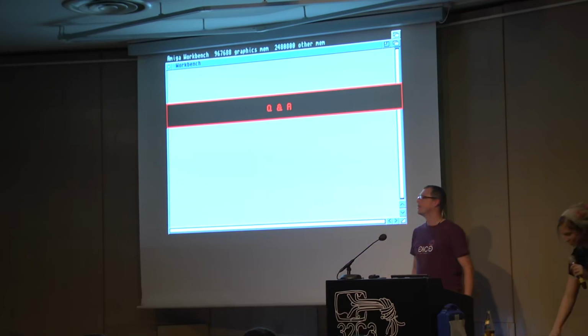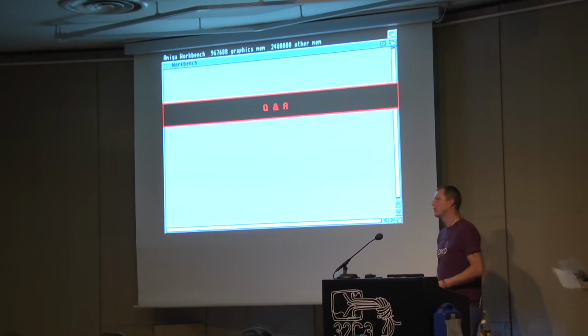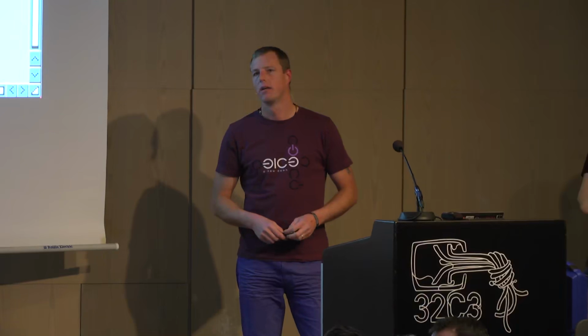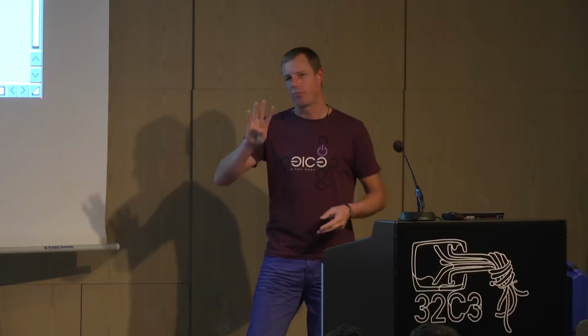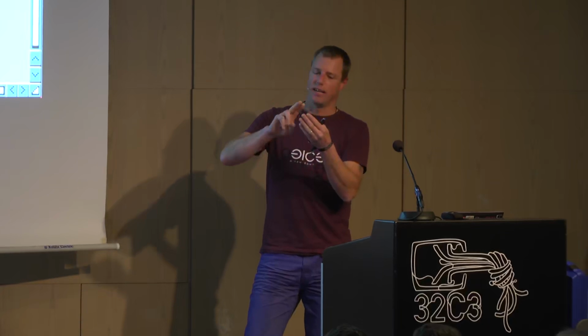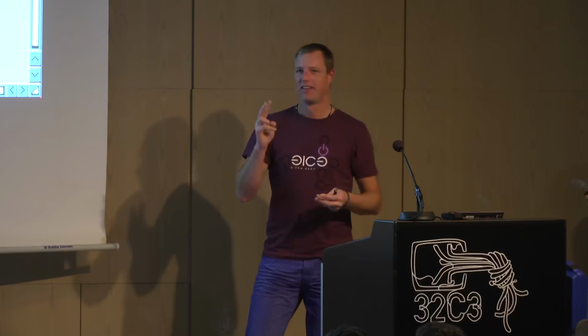Okay. I have a question regarding the sprites. You said it has hardware sprite collision detection. Was that like on the 64 where you only knew which sprite was involved in any collisions, or did it also tell you who collided with whom? Something in between. It always combined two sprites, so you then had to programmatically find out which sprite it was. But you had four sprites, so you could find out in pairs of two which sprite collides with the others. Okay? Okay. Yeah. Good.